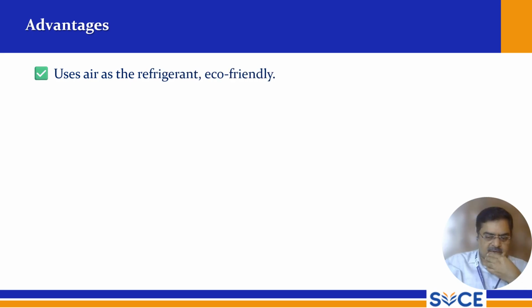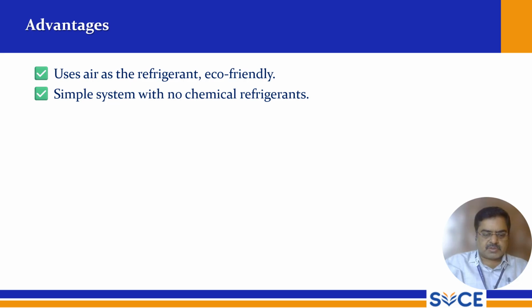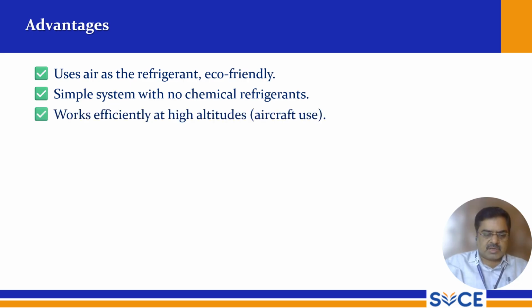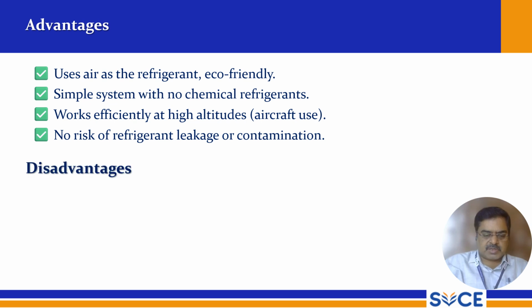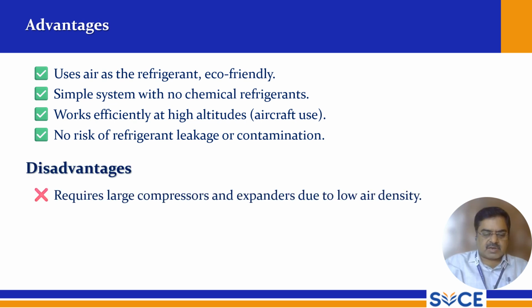Advantages of the open air refrigeration system: it uses air as the refrigerant and it is eco-friendly, and we are not using any chemicals here. It is a simple system with no chemical refrigerants, works efficiently at high altitudes, and is even useful in aircraft. No risk of refrigerant leakage or contamination. Disadvantages are that it requires large compressors and expanders due to low air density.